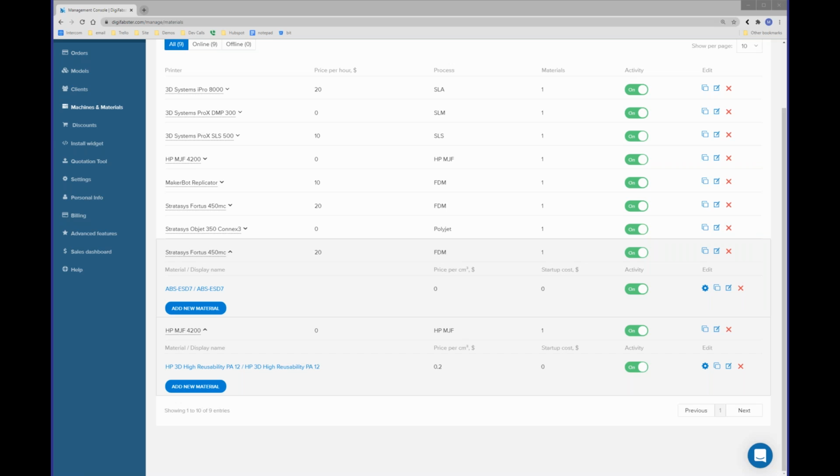So again, if we're printing a bird cage that's taking up our entire build envelope, so it's going to take us 8 hours to make this part, even though it's low volume, that should have a much higher cost associated with it. So the big things again to look at are the fixed costs of the material, the labor involved of removing the parts, cleaning up the parts, but also on top of that, we also need to look at the true cost of what is this costing to print. Instead of printing this, could I be printing X, Y, or Z and having a much higher return on investment?